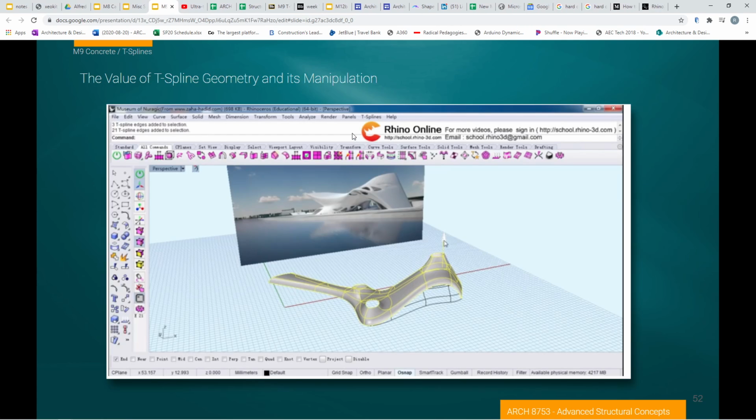Rhino is also very advanced in the concepts of T-splining. Just a brief idea about it: a T-spline is kind of like a three-dimensional NURBS curve. We have a control point, and then the shape is generated from that. It really reduces the complexity of the definition of the shape, and empowers the modeler with the tools they need to create really fast and high quality surfaces.